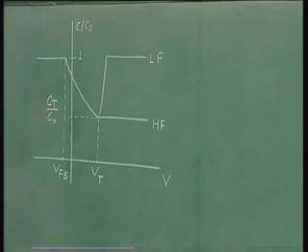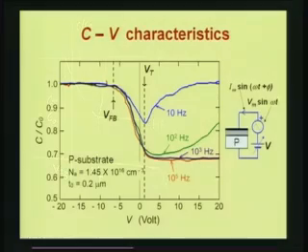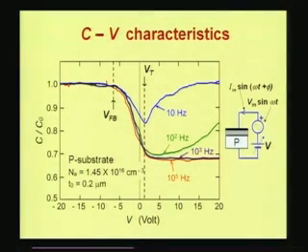If you look at the CV curve on the slide, we obtain the value here to be close to say about 0.68 or 0.69, okay, say 0.685. This is the ratio of the capacitance to the oxide capacitance at the threshold voltage point.